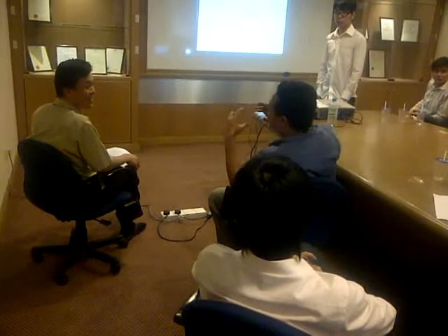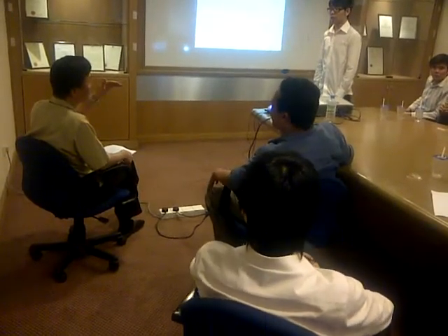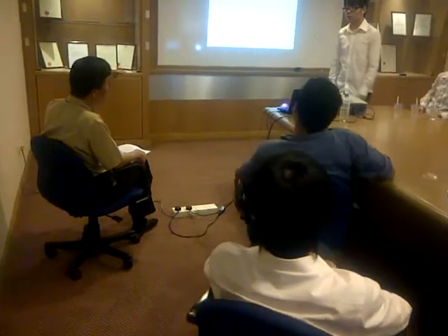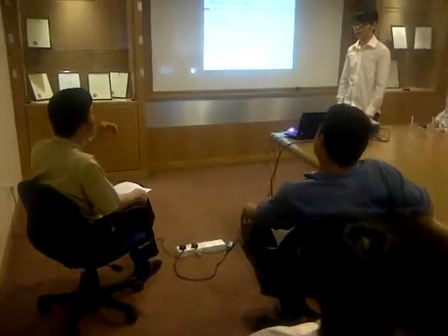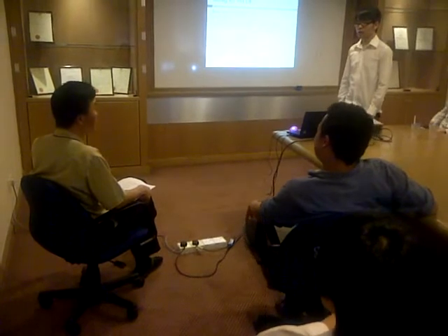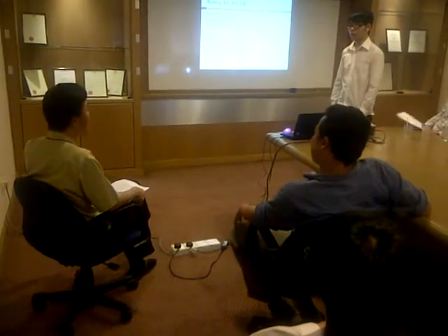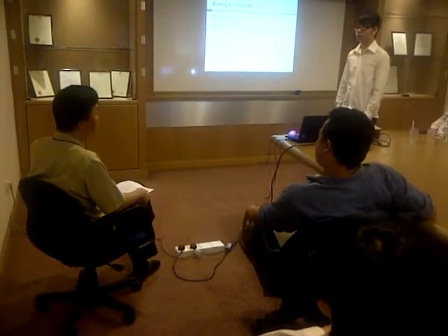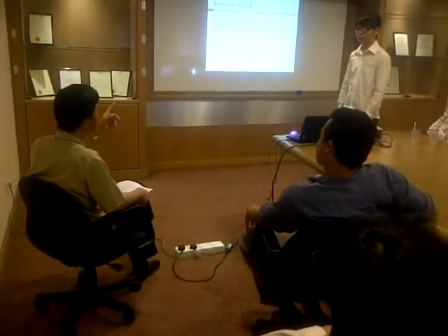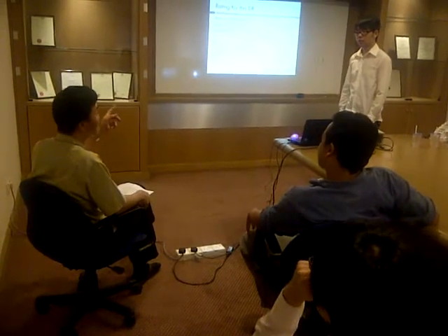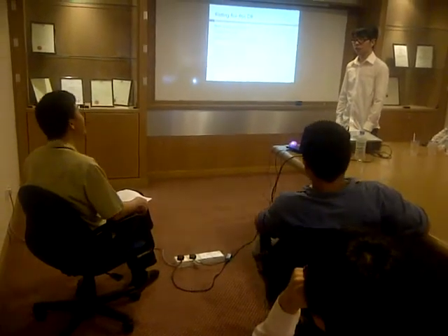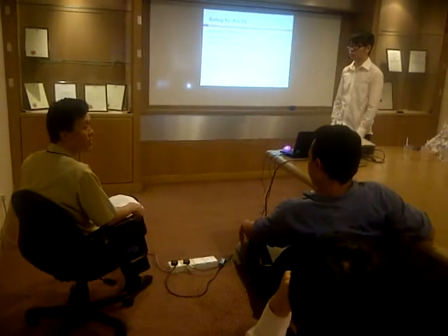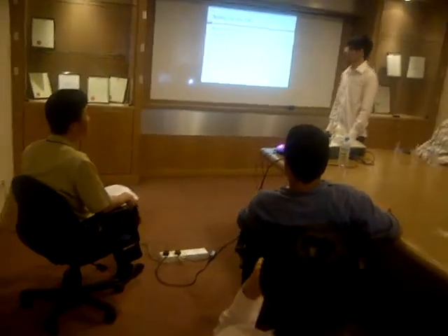No, they just put the power supply. But that one is maximum, right? Correct. You know the rule of thumb: 500 watt is near to 1 horsepower. You know our aircon, if it's running 9,000 BTU, it's only about 2 amp to 3 amp running load. If yours is 500 watt, let's say single phase, talking about 2 amp, it cannot be. Straight away, from the logic I know it is not right already.